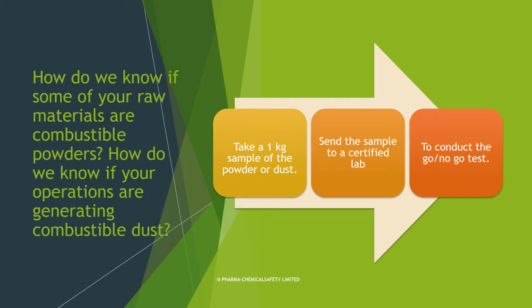Before, some companies and some specialists were using a worldwide database that had the different parameters of each material regarding combustible dust. But NFPA and OSHA don't allow that anymore, and that's okay. Actually, that's perfect, because in my experience, I found that the gap between the database and the results from the lab was so big. So there is a big gap. I don't recommend using a database, and actually you cannot use it by regulation anymore.